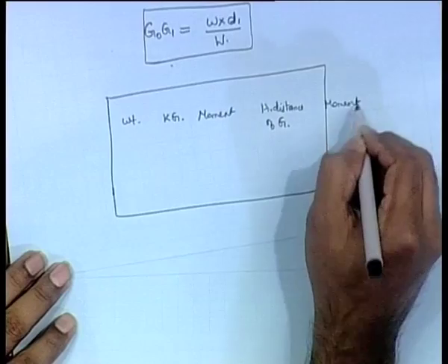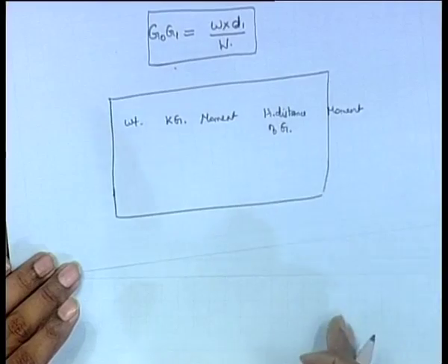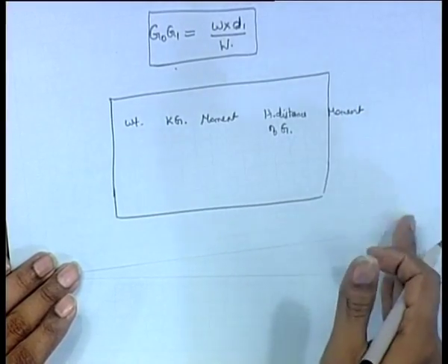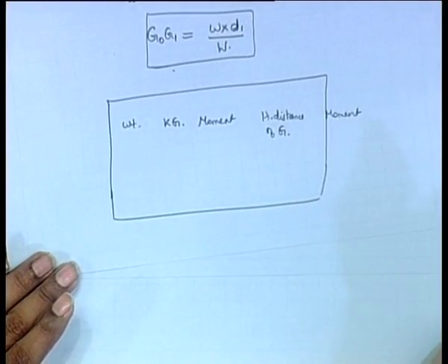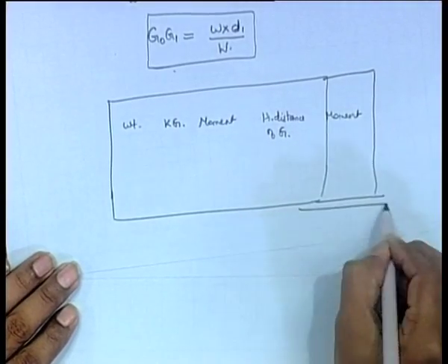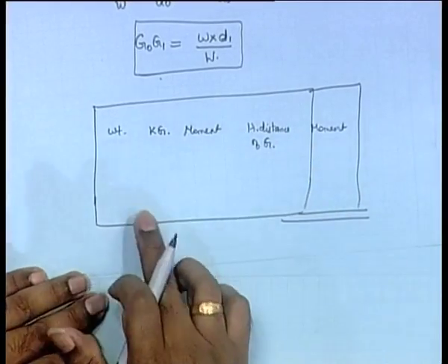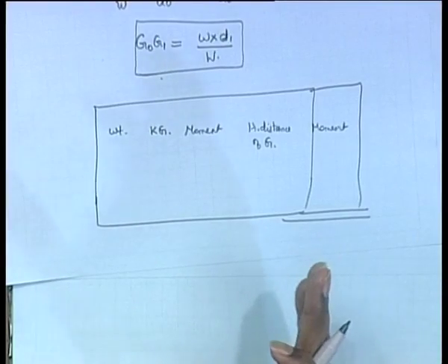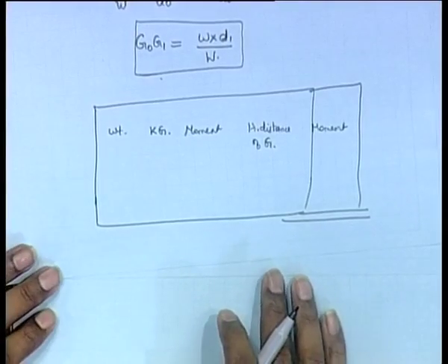You can do two things, you can put the port moments as positive and the starboard moments as negative, or you can put different moments, but a concise way of doing it is port moments as positive and starboard moments as negative, so in one table like this you make the whole thing. And this moment divided by the total weight is the answer. Suppose this is the problem, you just have to solve it, just written in a different fashion, that is all.